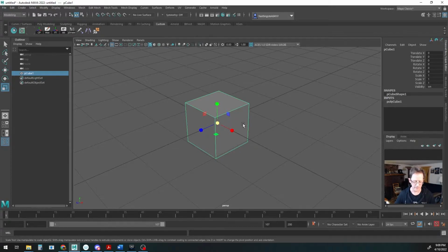If we press R, that's scaling, and again we have a different set of gizmo. Right in the middle we can scale it all symmetrically. So X, Y, and Z are changing their size, and scale X, Y, and Z always start out as 1. We can scale it along this one, make it super flat. We can even reverse it.